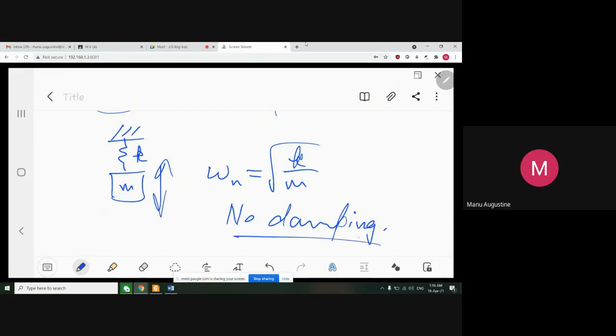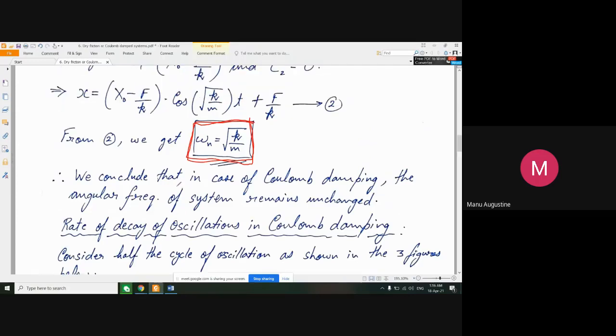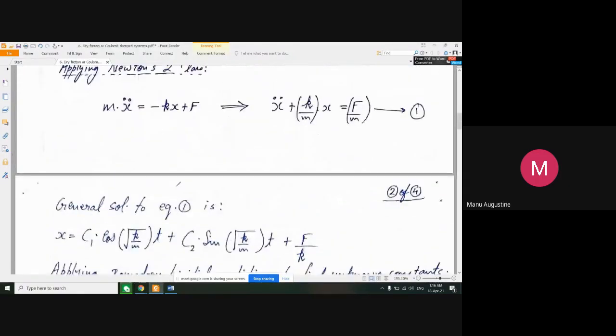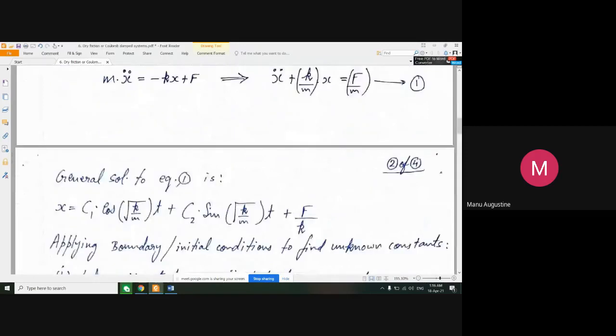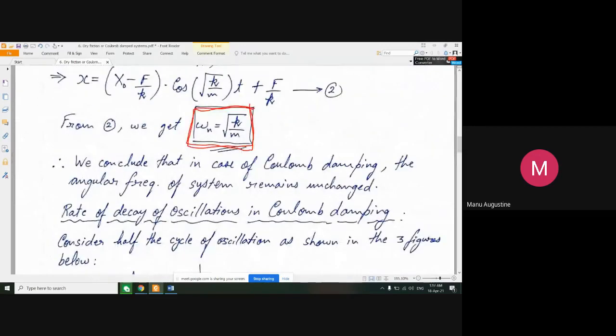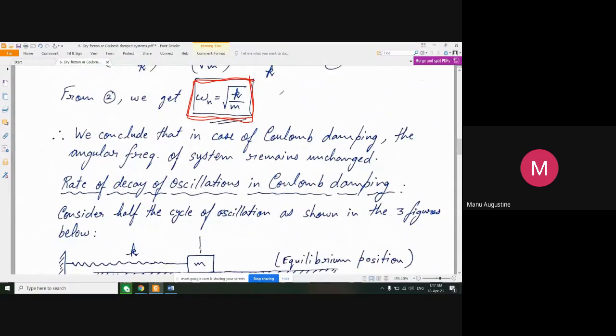So omega n is equal to under root k by m, the frequency of a simple spring mass system when it is devoid of any sort of damping. But then you did a lot of mathematics here. You put up the damping case also. You brought friction into this. You developed the differential equation. You solved the differential equation, compared it with SHM and voila. What you are looking at is the same thing sitting over here as if there were no damping.